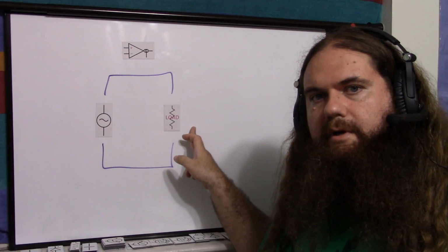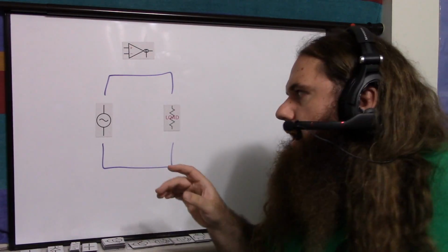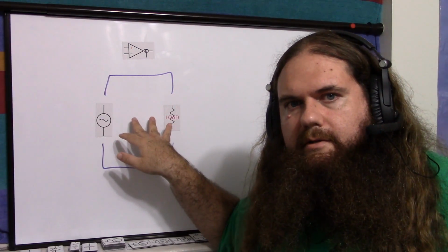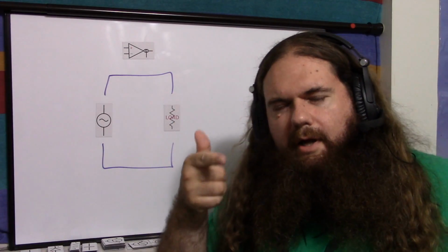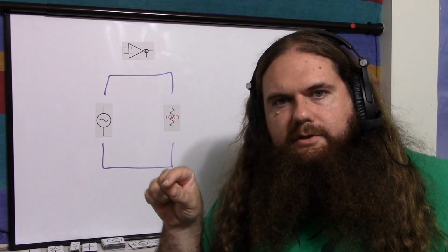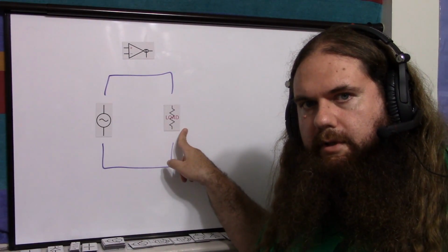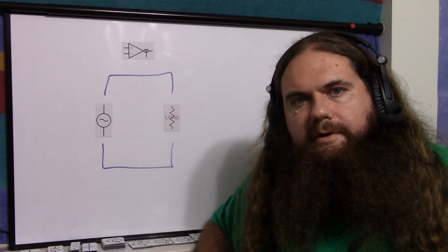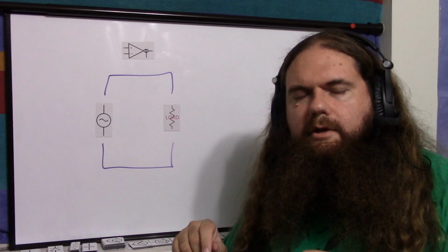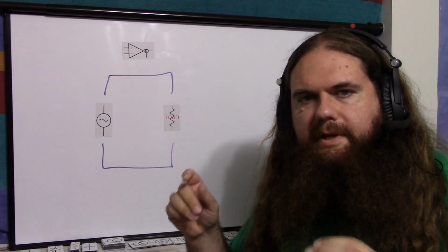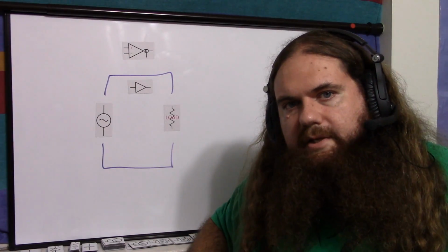So this is unbuffered, because if you hook it up to a microcontroller pin, if you hook it up to a speaker, you're going to get different signals. And you may have heard of loading the output of a chip or something. If the signal generator, like this is an issue. Remember, I showed you in the previous video where I plugged in my oscilloscope probe and it messed up the signal? I was loading the signal generator. If you have a high power load, low impedance, and you hook it up to a signal generator, that alone can distort the signal because it'll mess with the internal components here. You know, you get parallel capacitance, parallel resistance, it messes with voltage drops of BJTs or whatever. So that's another reason to use a buffer, is so that you don't mess up your signal with a load.